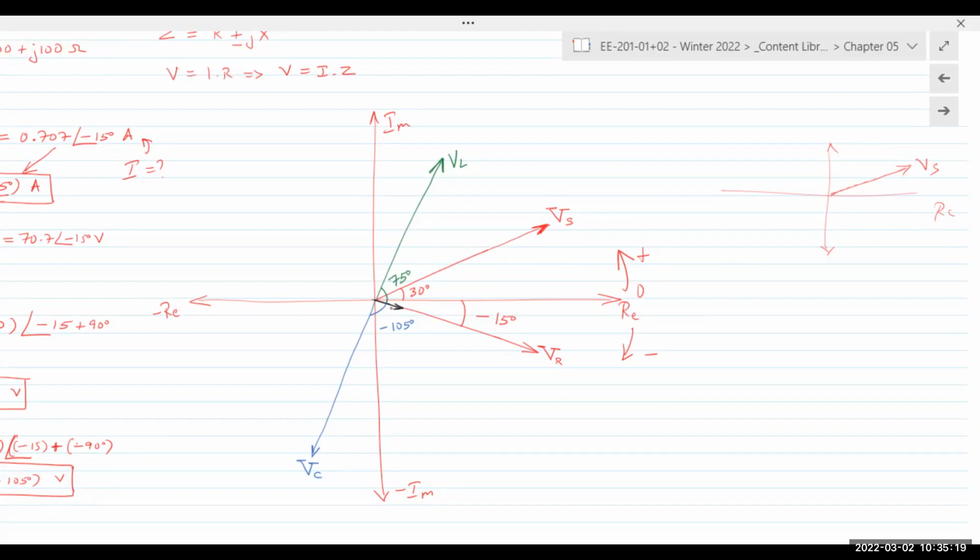And because the inductor and the capacitor share the exact same current, for this case and only this circuit particularly, the phase difference for an inductor and a capacitor voltage is 180 degrees, completely out of phase, inverted. And that is only because they share the exact same current. If they were connected in parallel, or some other neither series nor parallel, as you will see in the next problem, then it would not be 180, it would be something else because the current would not be the same. Make sense?